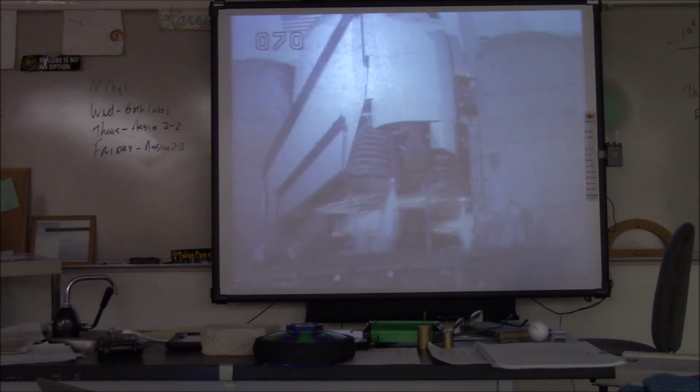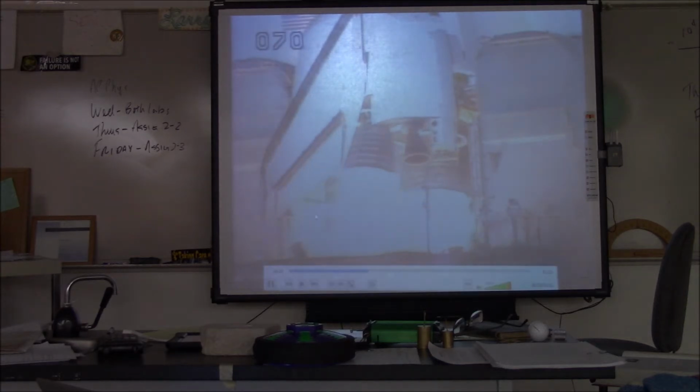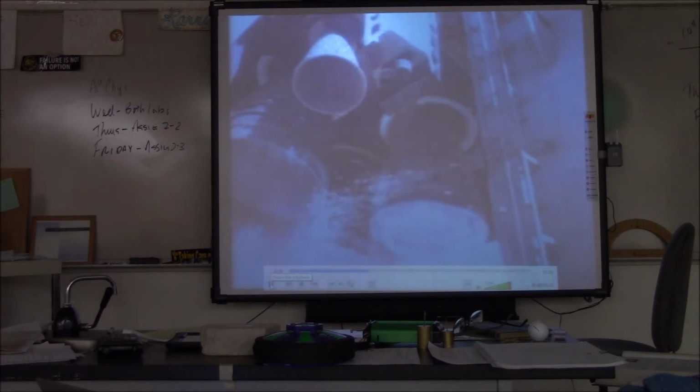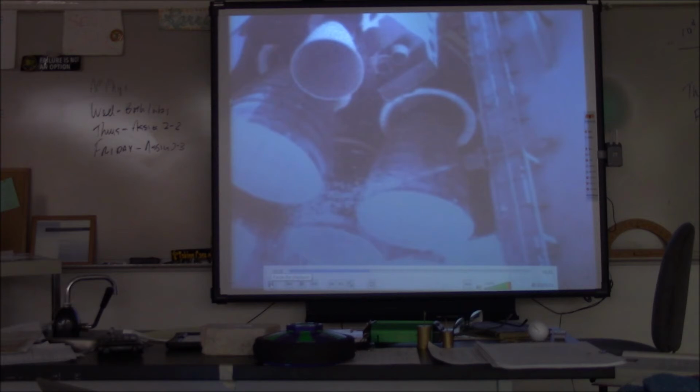Hydrogen igniters under the main engines are used to ensure that any hydrogen flowing out of the engines prior to ignition is burned off as it emerges. This prevents the buildup of a potentially hazardous cloud of explosive gas. That would be bad. At 6 seconds before liftoff, the 3 main engines are ignited. Shock waves coming out of the throats of the nozzles cause them to vibrate momentarily. At T-minus 3 seconds, the main engines reach 90% thrust.